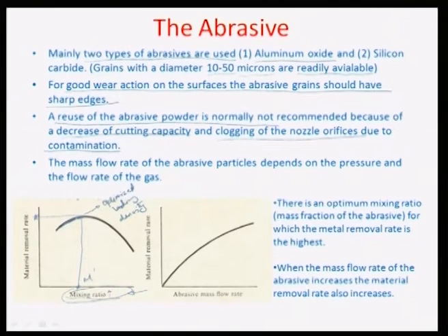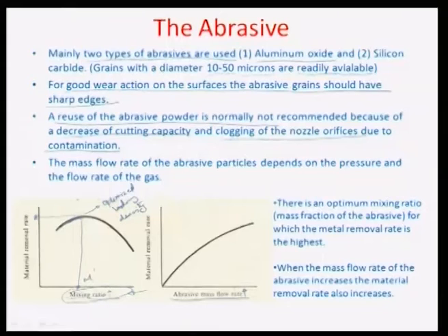So, there are some other interesting factors. For example, if the abrasive mass flow rate is increased, the material removal rate would almost always increase because of the increased Z, the number of particles impacting per unit time, which would increase because of the abrasive mass flow rate. So, this is all about how you design or select the abrasive for operating the process.